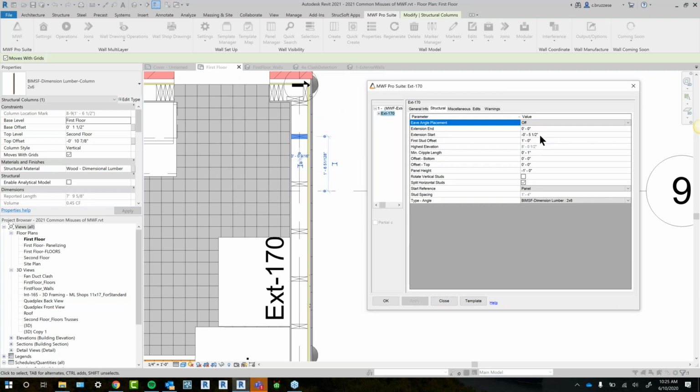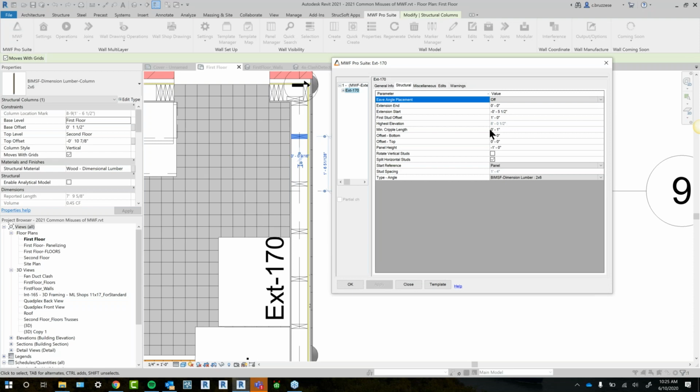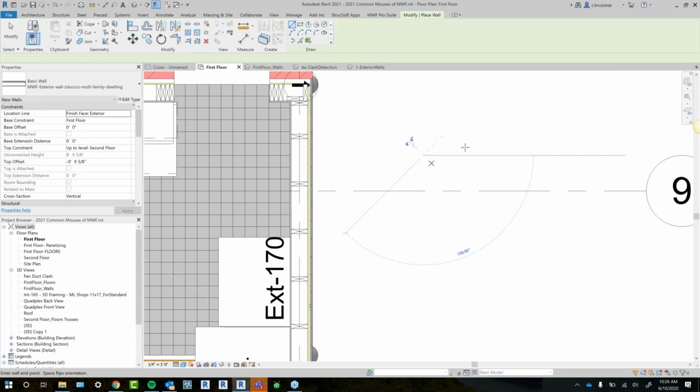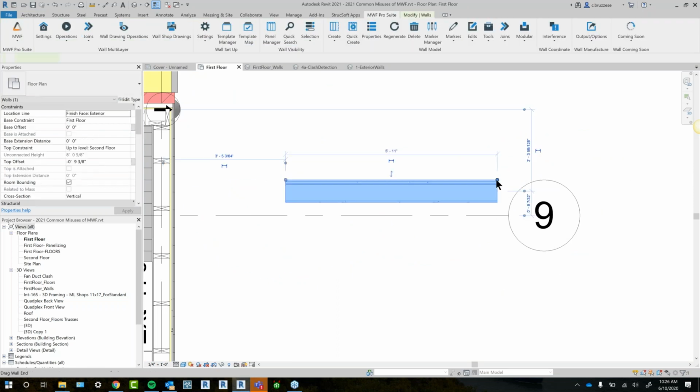Excuse me. So this here is what the joins control, basically. If you are changing the main wall, changing the join around a bit, you're basically changing the extensions on either panel, and it'll create with a negative offset, and that's just how we know to pull the panel back for the join. So if you are modifying templates, saving new ones, we always recommend saving it on a wall that doesn't have any connections to it.